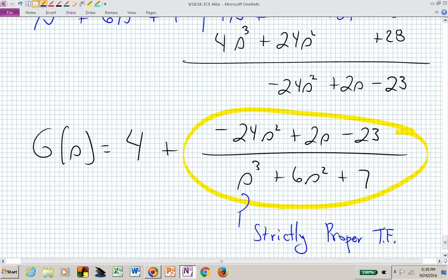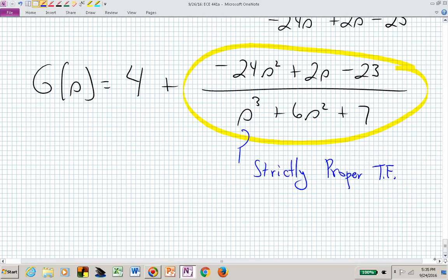We know how to put that into a state space representation, the A, B, and C. And this piece right here is actually our direct feed-through term from the input to the output. Now, an input u gets scaled immediately by 4 into our output, and so this is going to be our D matrix, which is 4.